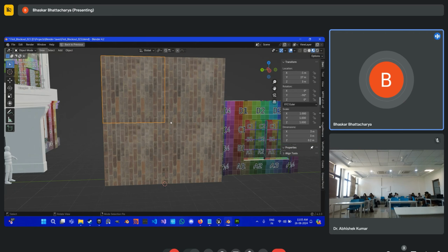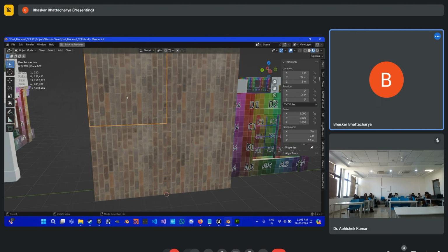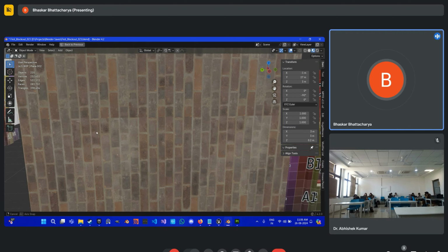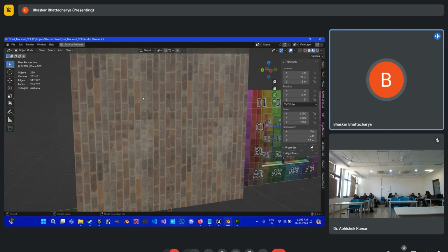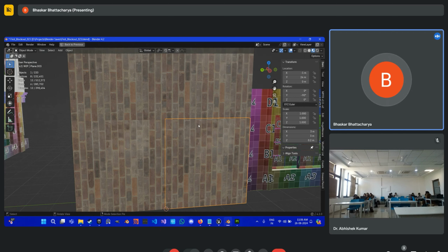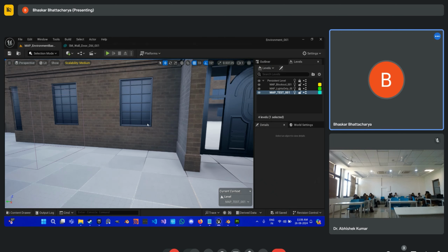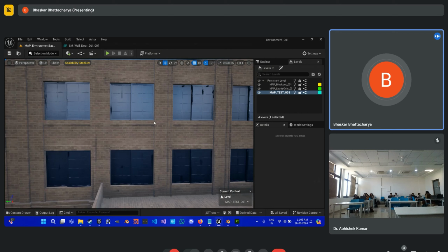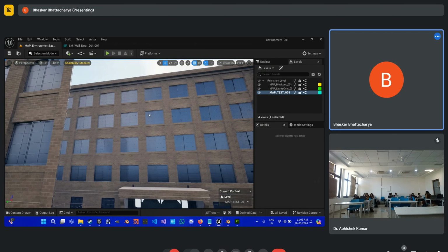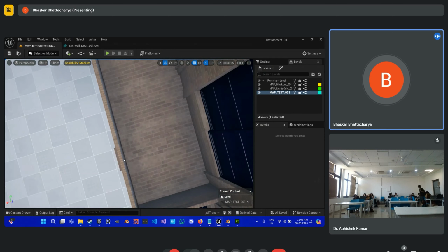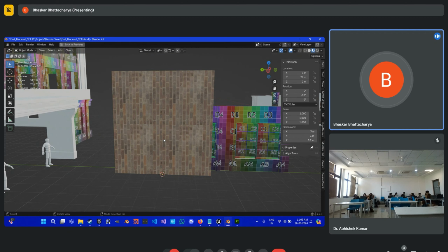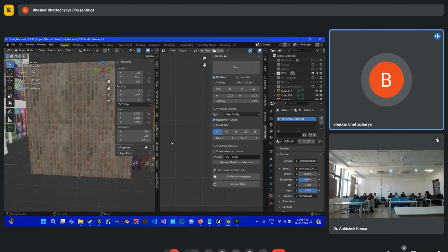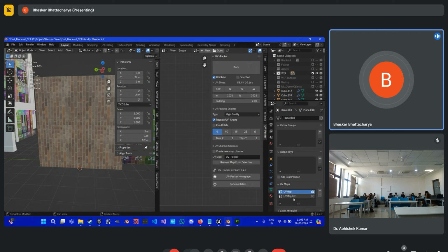And also our UVs are rotated, which is not ideal. We will fix that eventually. But the point is we have visible seams between these pieces, and as you can imagine, this is a problem. We cannot have visual seams like this. And if you see all of these assets, there are no visible seams between our meshes. Nowhere will you be able to spot a seam. So what we need is a UV unwrap which hides all these seams. For that, we will come to the second UV channel.